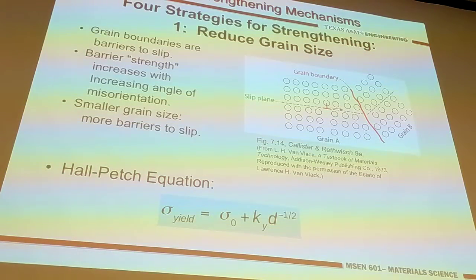It's not dislocation density, because in the latter case, the 4th strategy is cold work. It generates a lot of dislocation. Okay? Through generating a lot of dislocation, at the same time, those dislocations get entangled. So it's not about dislocation density, rather about dislocation motion. Okay? You can have dislocation, but you don't want them to move. Or you can have less dislocation, and still you want to make sure they don't move fast or not so easily, right? So the 4th strategy, it's reduced grain size.